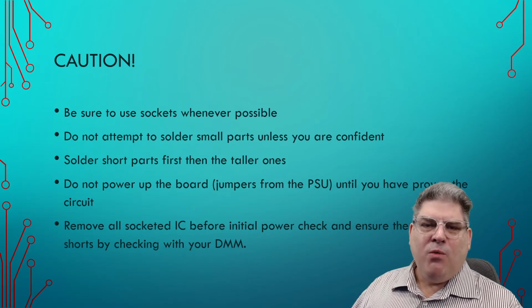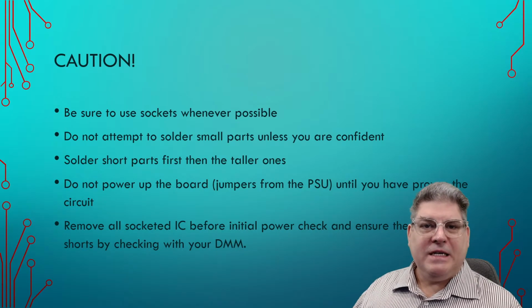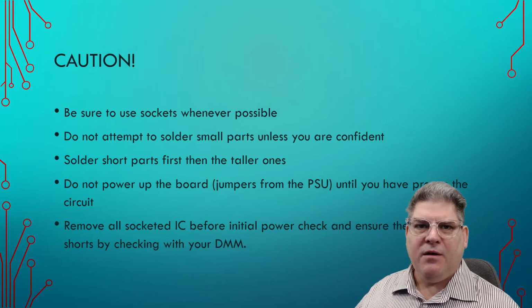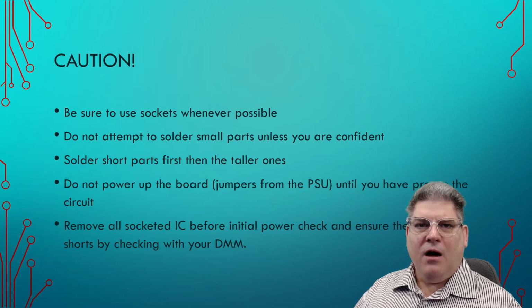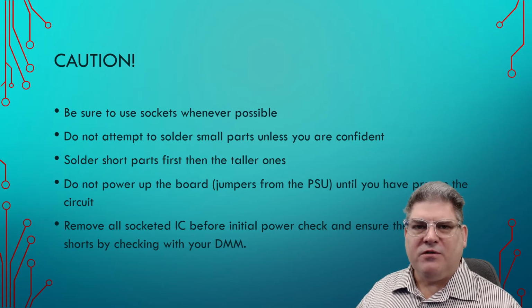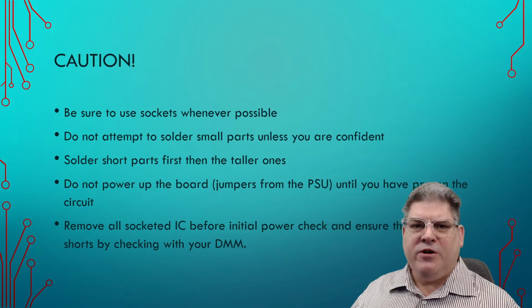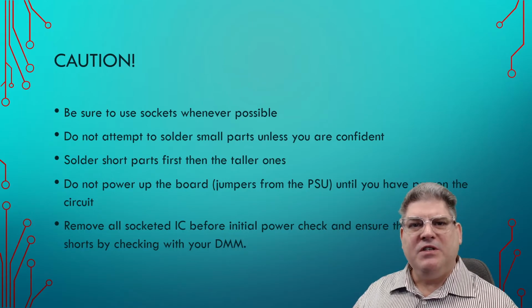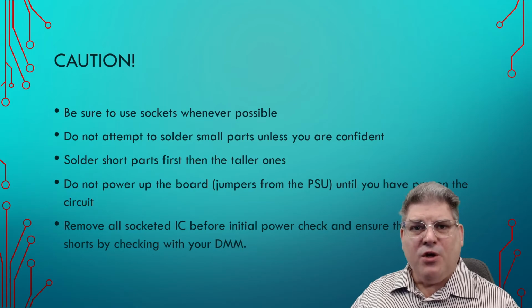One of the things that we want to do when we are testing a circuit board is we never want to just power it up and fire our voltages down the rails at the sensitive pieces of electronics. So what you want to do is check for dead shorts on the power supply, between VCC and ground. If you don't have several ohms of resistance, you know there's a problem.